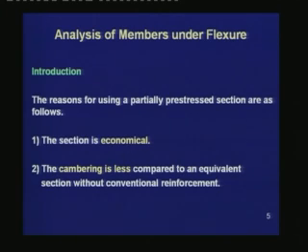Next, what are the reasons for using a partially prestressed section? The reasons are as follows. First, a partially prestressed section is economical compared to a fully prestressed section. We do not need as much amount of prestressing steel and anchorage units as compared to a fully prestressed section.